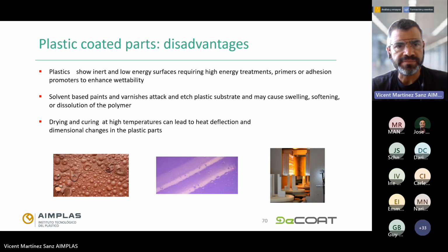But there are also some disadvantages related to plastic coated parts. We have to bear in mind that plastic materials show inert, low-energy surfaces that require high-energy treatments in order to enhance wettability. That means, in most cases, the application of primers or adhesion promoters in order to assure good adhesion or bonding of the coating layers.